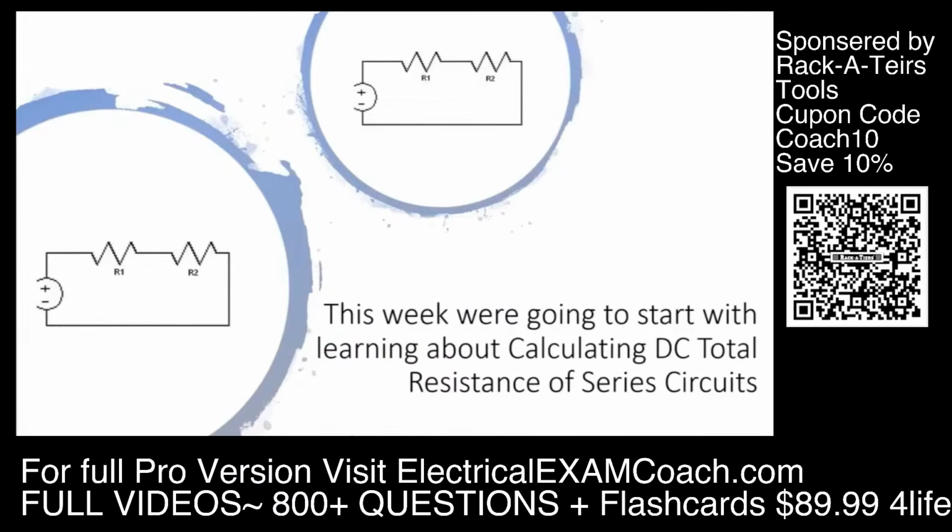If you look at this circuit here, they're both the same picture. If you look at it, you have the battery symbol there, and we're going to go with conventional flow, saying it flows from the positive through the resistors to the negative. Electron flow would be from the negative to the positive. But our example here shows it from the positive, going through the resistors, coming back through the negative. We're going to learn how to calculate total resistance of DC circuits. We're also going to learn how to calculate voltage drop across the DC circuit.